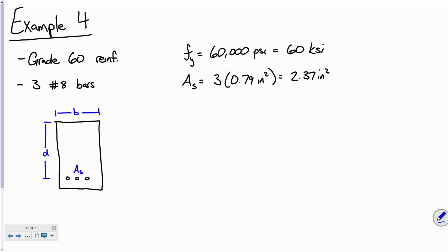Now, the total height of the beam we call H, but we're not going to care about that for what we do here. Now remember, when we draw a bending stress profile, theoretically what it would look like is this. We would have some neutral axis. We define the neutral axis by saying it's some depth C from the top of the beam. That's the notation that we use, okay?